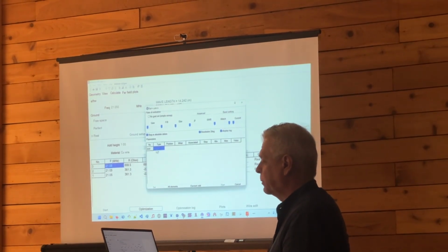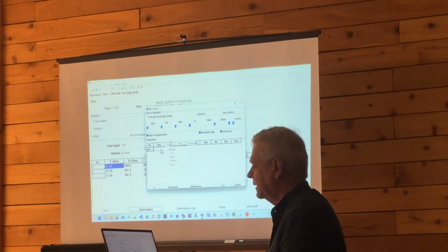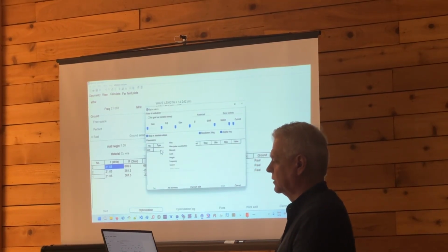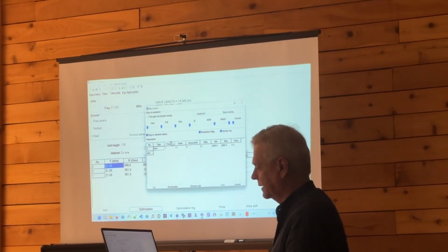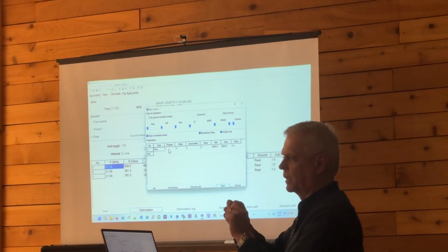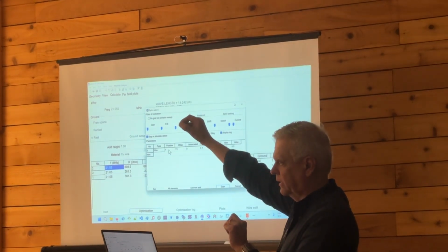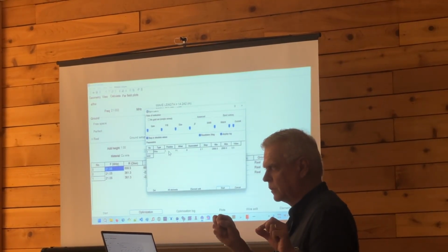Now, remember, this part right here was where we're going to tell it what the program can tweak for us. We click here, and we get a bunch of options. Of particular interest, you see wire, that's the one we're going to select. Well, we have 2 wires. The program thinks 67-foot wire, the main one, that's wire number 1, and the little 2-meter pigtail.